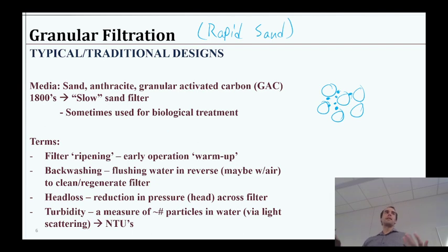And so we can measure that head loss really just by looking at what level of the water is above the media bed. So that's called head loss when we have a higher pressure drop. That hydraulic head required is increasing from what a clean filter looks like.